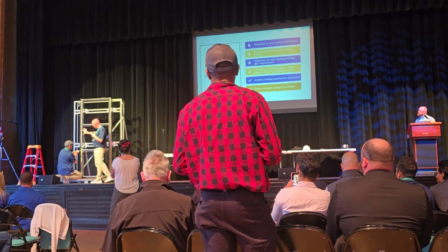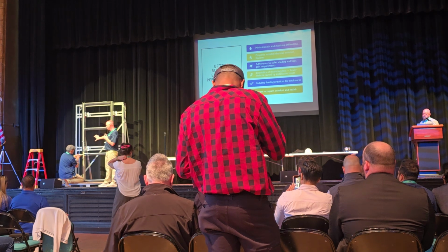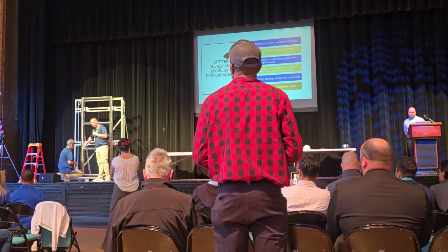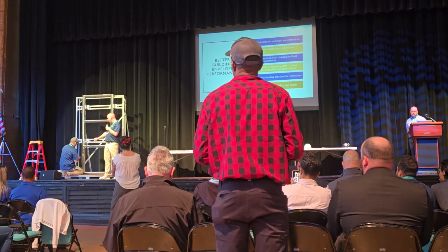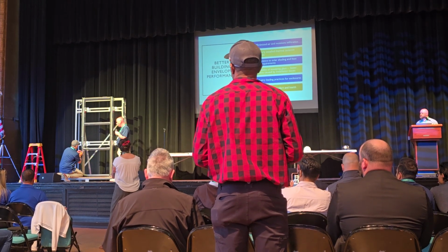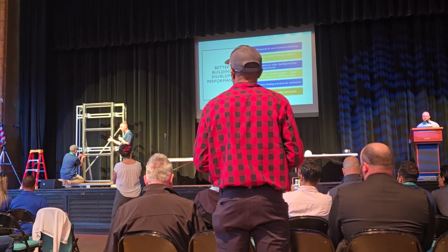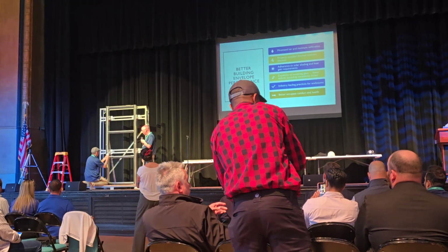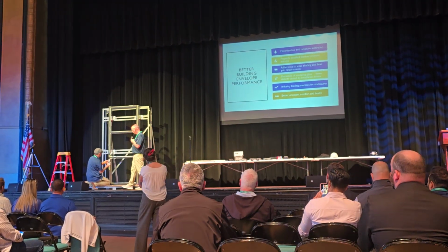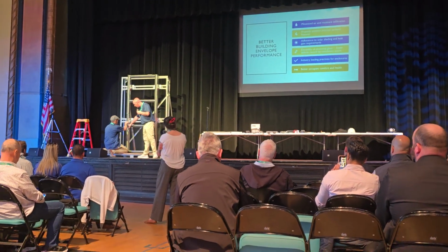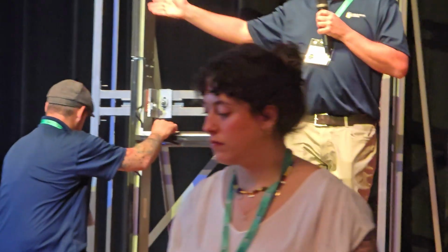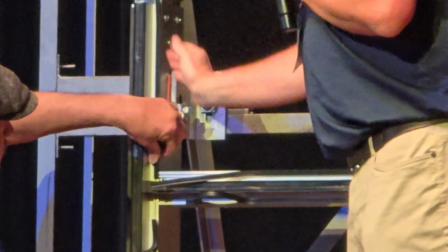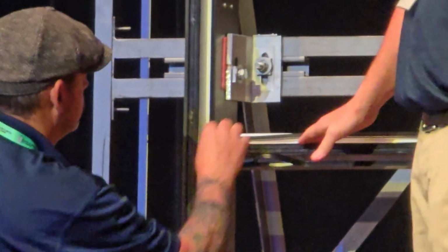Next, since each window opening is considered a zone, everything is its own zone. So right now, Billy's filling three sides of the ceiling and placing a zone dam inside the corner, which creates our bridge from top to bottom, so water cannot go to the next opening. Once he tools over top of this and underneath it, it gets tooled and slipped out, almost like a ramp, to funnel any water that was able to possibly get in down the channel and over onto the horizontal.